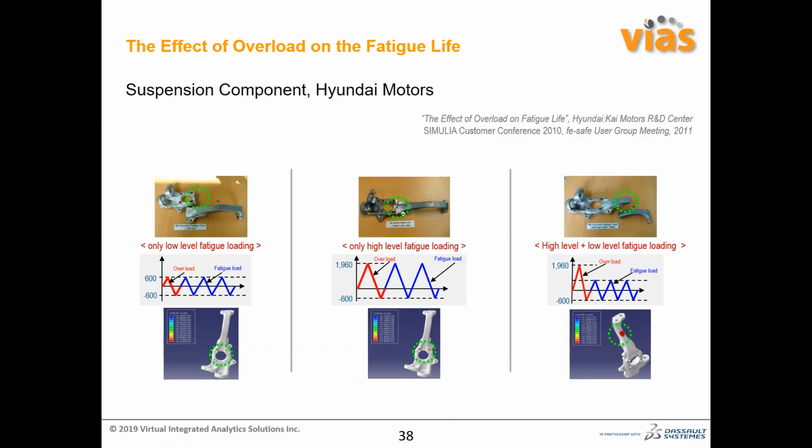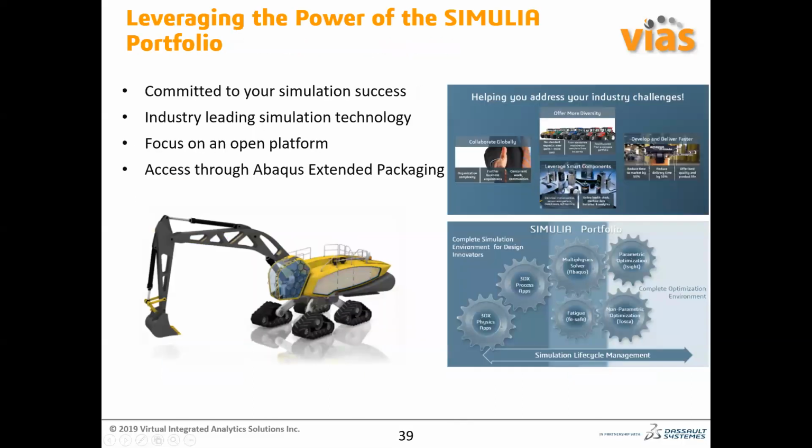And not only the history, even the manufacturing stress, like residual stress, or if you're doing some metal forming procedure, there will be some initial residual stress that also plays a big role in finding the optimum fatigue life of a product. Generally with the normal fatigue life calculation, we neglect all those things. So here fe-safe can take into account all those things, give a very detailed understanding of the fatigue life, and calculate accurately the fatigue life of a product.